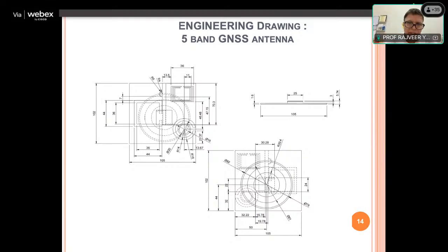Now, if you see the FSS dimensions, these are nothing but the same theoretical formula of a microstrip line. If you elongate, the length and width will be deciding the value of L and C, and based on the value of L and C, we will be able to say how much the resonant frequency is.